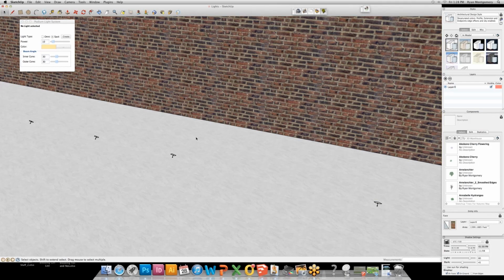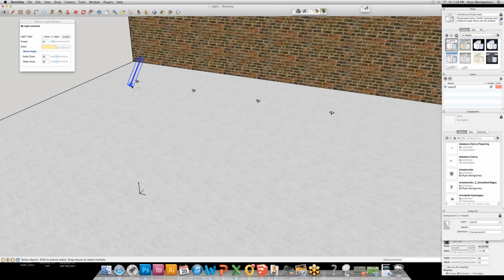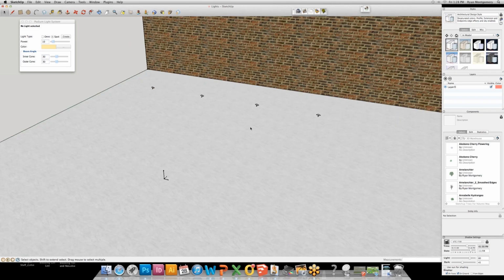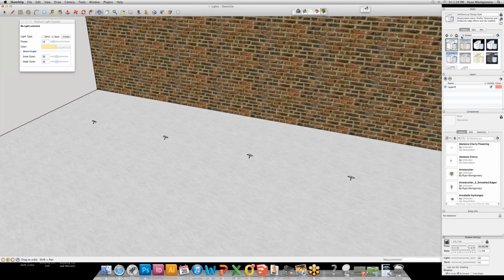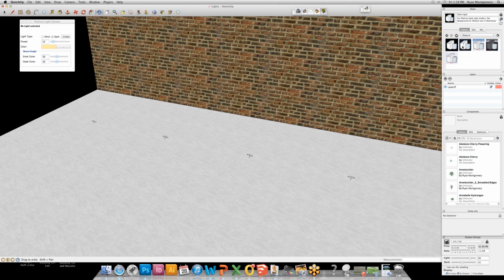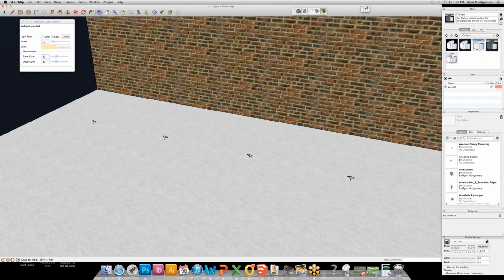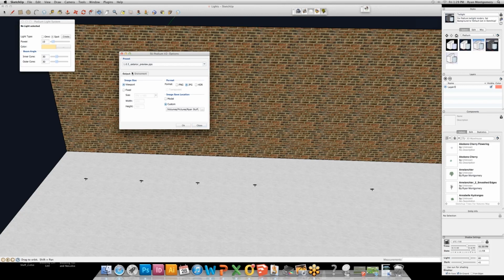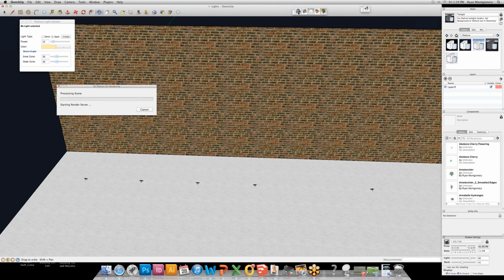So with night scenes, you're going to want to do these a little different. If you just click render, it's going to be daylight and you can't tell what's going on. But if you go over to your styles, Podium adds what's called Podium styles. And these are all different nighttime sky simulations that you can do. So I'll click on that, pick my scene, and then I'll render the viewport, export as a JPEG. I'll do exterior preview, and that looks good, and then I'll click render.